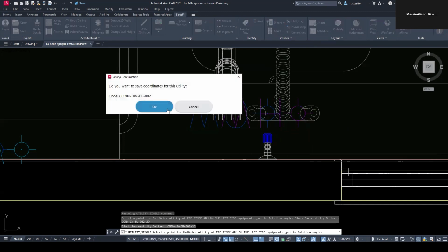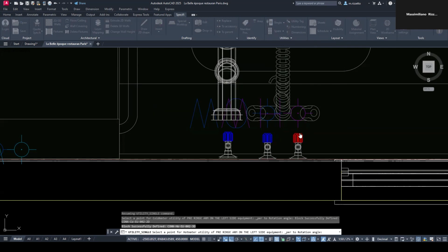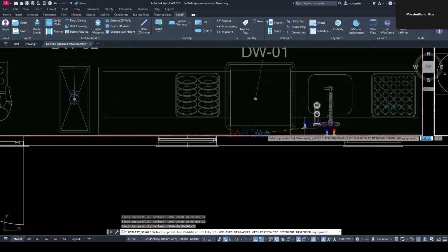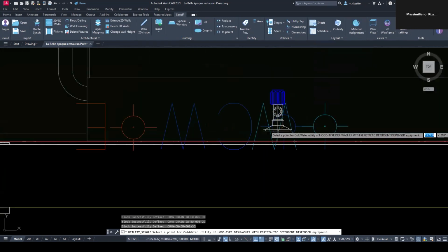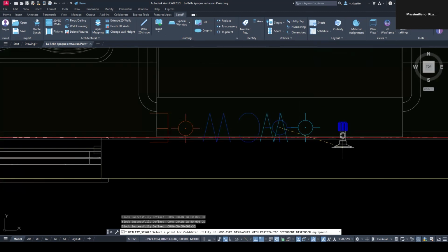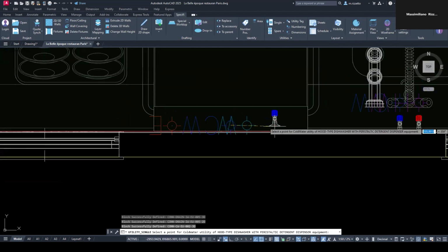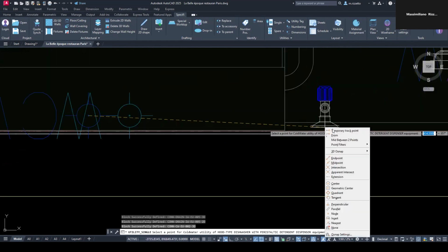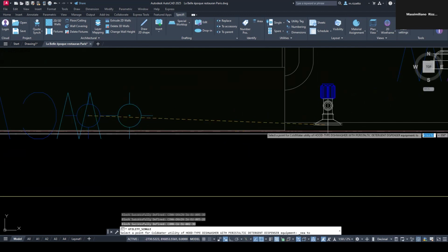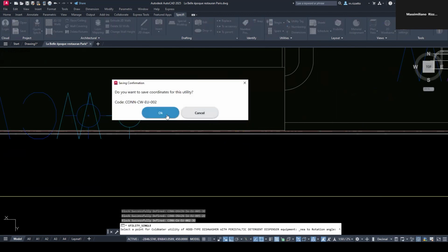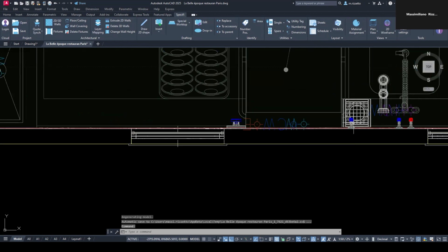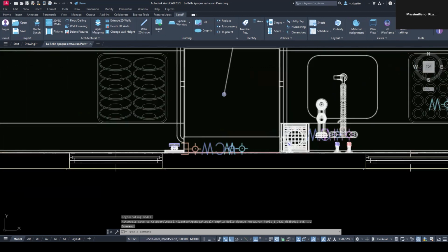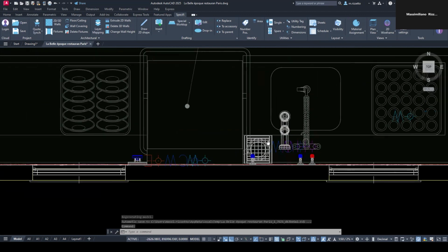And now for hot water I can use perpendicular again. I'm using Quick Snap with the shift button, or control and right click. And here again, another one, but in this case maybe I can insert over there. I use nearest, so I can put it here. At the end, it doesn't ask for the waste.